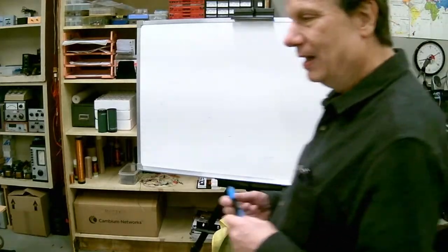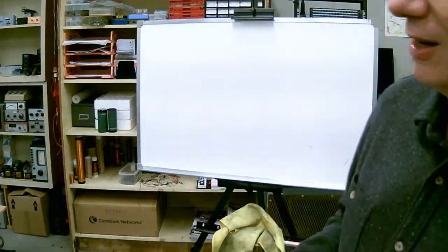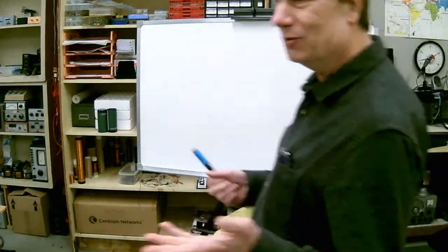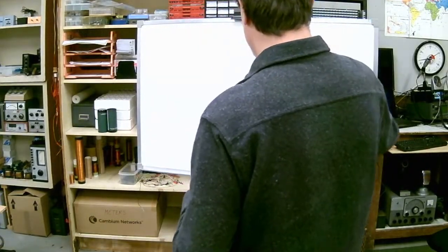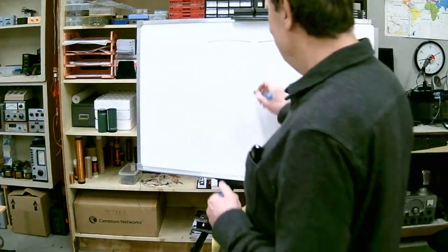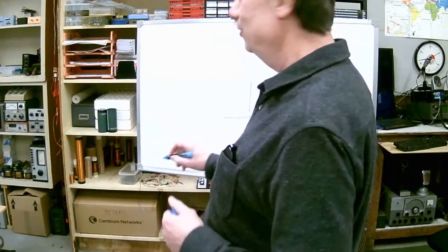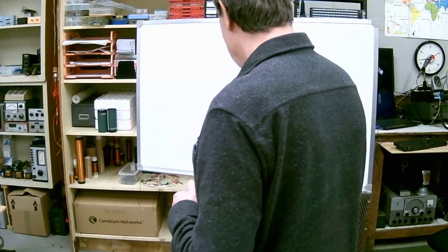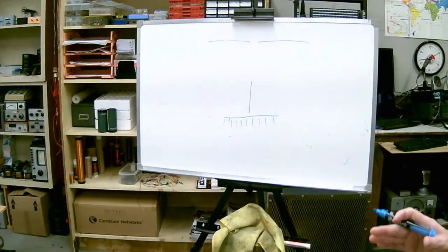Now there are trillions of different types of antennas, but traditionally there were basically considered two fundamental types. One was a Hertz antenna, which is the half wavelength dipole that we talked about. And then we have the Marconi antenna, which is a quarter wavelength, and it works across a ground. So assume this is an infinite conducting ground surface, like if the earth were paved with copper.